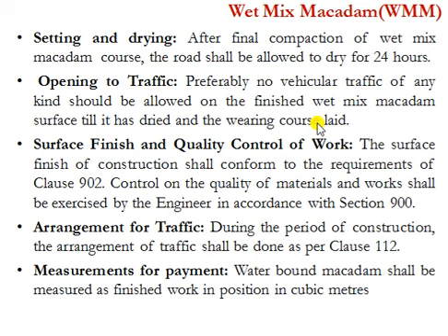So after testing the compaction and level of the wet mix macadam, the road should be allowed to dry for 24 hours. During this time, no vehicular traffic should be allowed on the road. The vehicles are allowed only after completion of the road. So the road will be finally completed after laying of the wearing course.